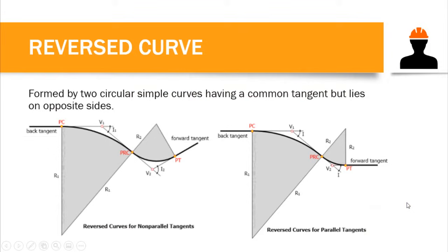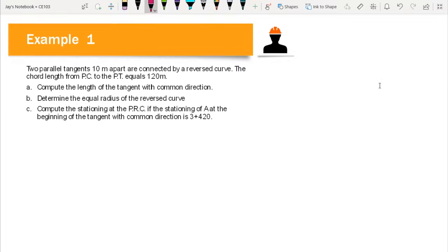In this video, again, we will try to solve the elements of the curve. If you missed it or do not know what these elements are, I have posted the link of my discussion on the derivation of simple curve elements. So why do we need to compute these elements? We need to determine the values of the elements of the curve because we will be using them to lay out our curves in the field.